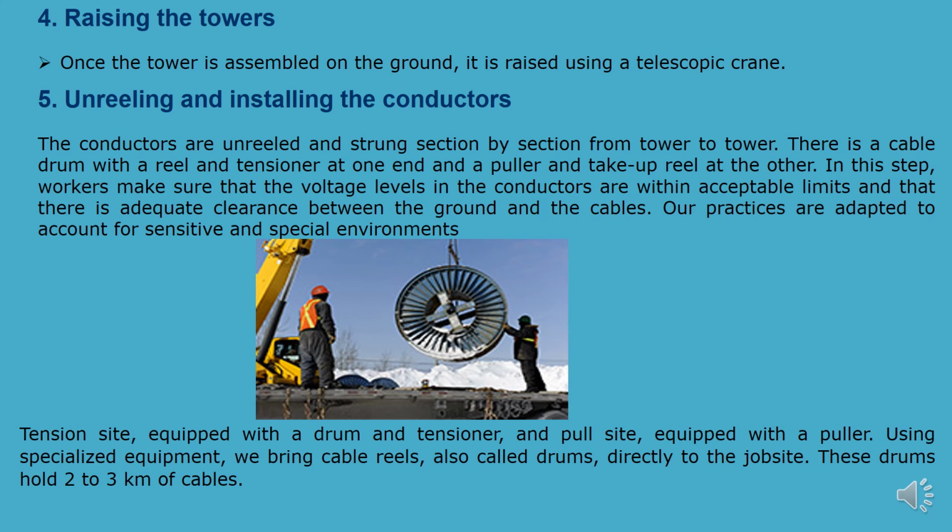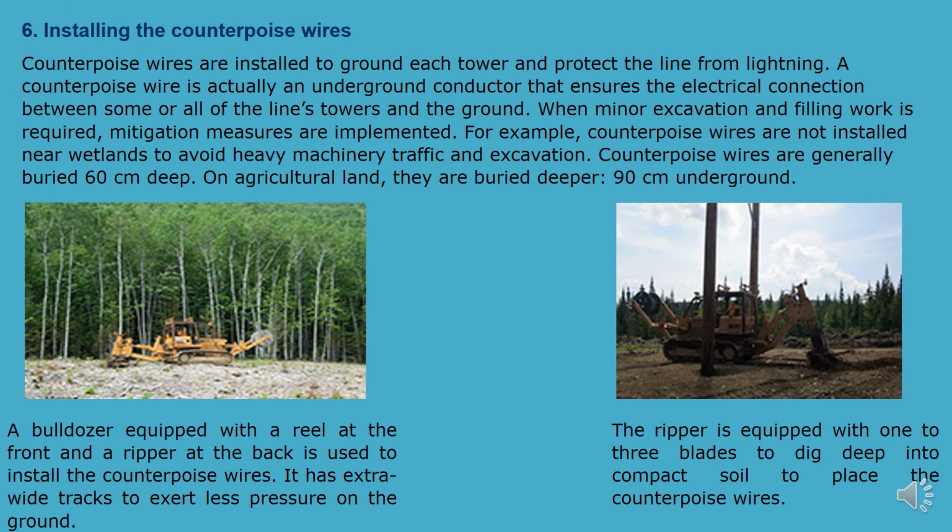By using this equipment we can connect the cables from one point to another point. We have to pull it properly so that it is not deflected and there is no movement, right? So we have to connect properly, that is unreeling and installing conductors.